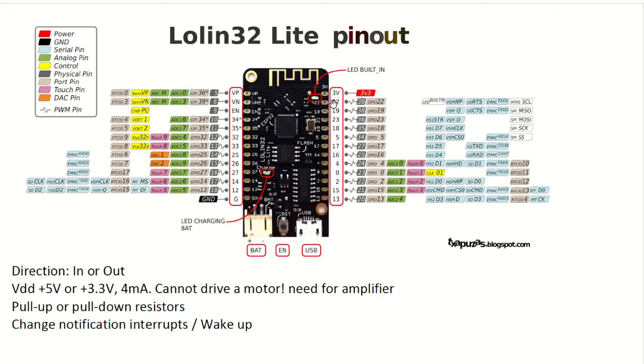And as you can see here, the digital input-output are called general purpose input-output. You can see 13, 0, 4, etc. Some of them, like these ones, can be put only in input, because for a digital input-output, you must first choose the direction, whether you are using it as an input or an output.